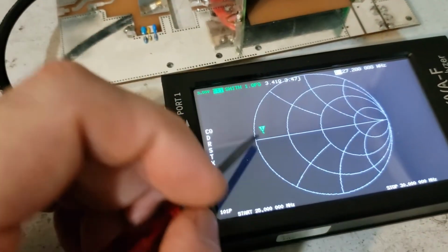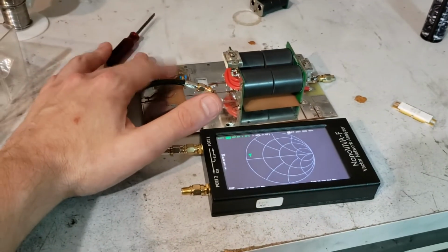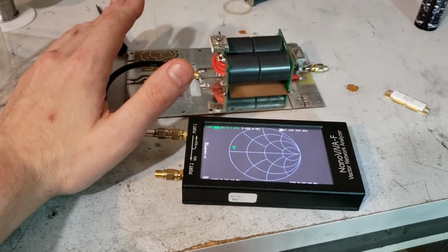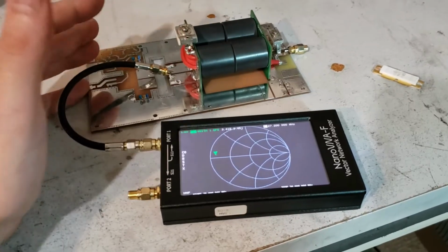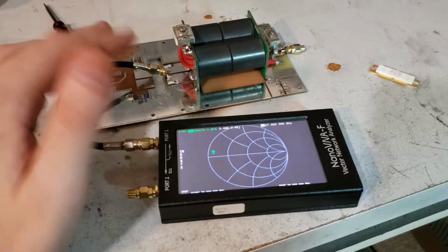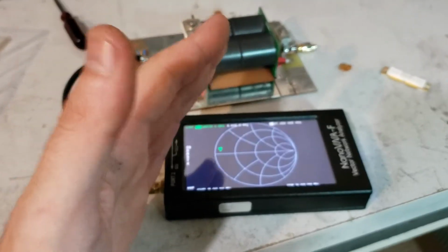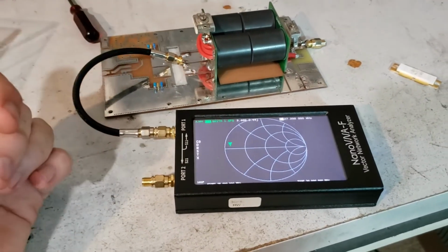The resistive value is going to be lower as well. So the general idea here is to figure out what ballpark impedance your transistor is going to need, and pre-tune your capacitors for approximately that impedance value, or go a little bit higher, because higher is going to be lower power output, less strain on the transistors, all that good stuff.